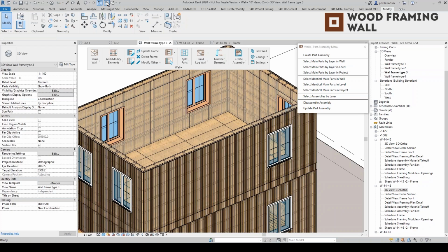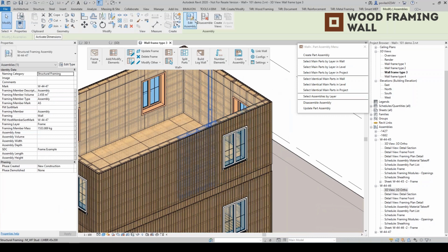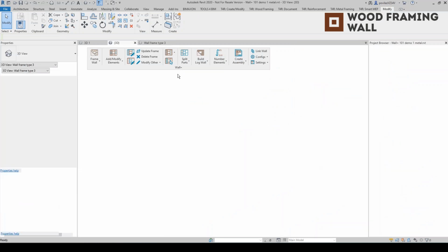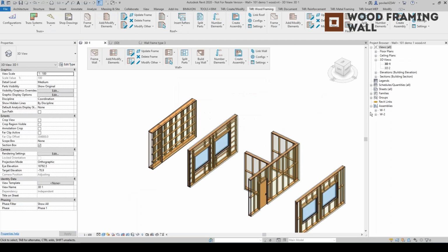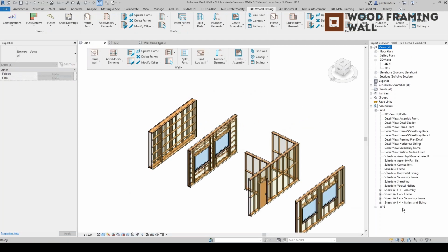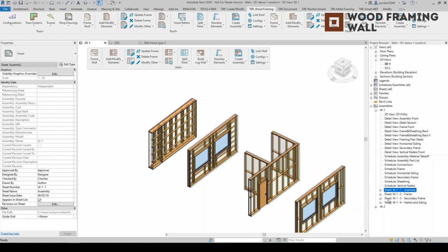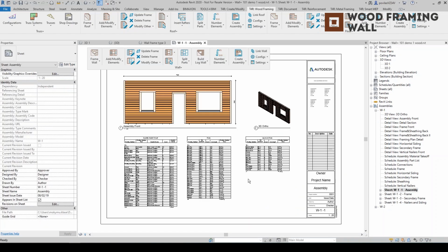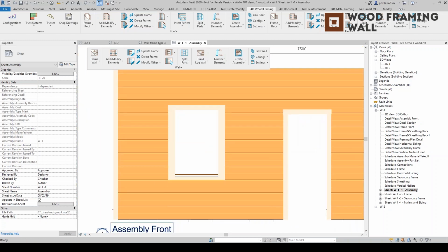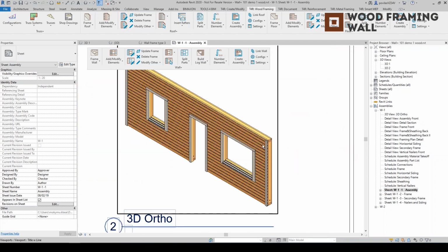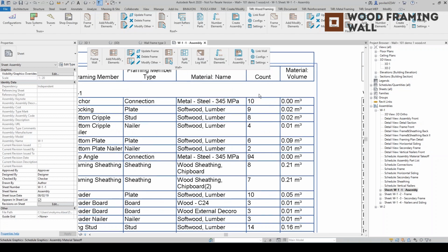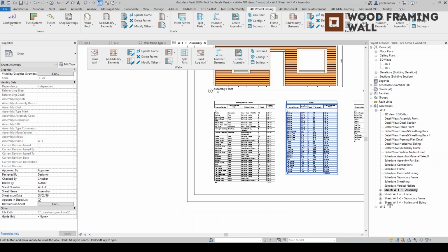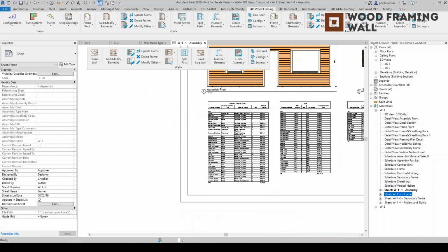Okay, so we have our assemblies created. You can disassemble, you can update assembly, etc. So let's go back to the timber framing examples, and I believe there were some drawings generated for those. Okay, so there are a few drawings. So if I go to drop-down menu, those views were placed automatically on those sheets. Okay, so sheets are created also by the tool. Okay, so in this case, I have horizontal siding drawing, 3D view, schedules that describe everything, all detailed information is input here. Okay, so another sheet for mainframe.